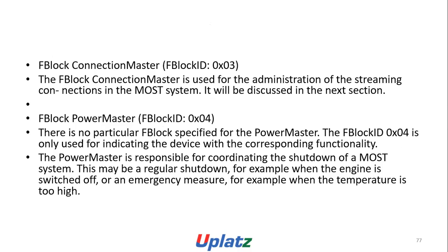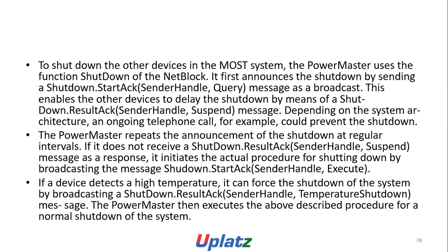The power master is responsible for coordinating the shutdown of the MOST system. This may be a regular shutdown, for example when the engine is switched off, or an emergency measure, for example when the temperature is too high. To shut down the other devices in the MOST system, the power master uses the function shutdown of the NetBlock. It announces the shutdown by sending a shutdown start, acknowledge, query message as a broadcast. This enables the other devices to delay the shutdown by means of a shutdown result, suspend message.